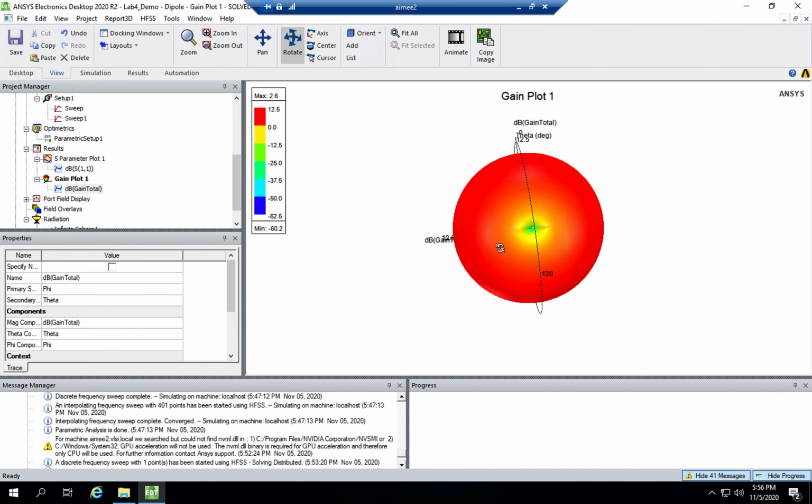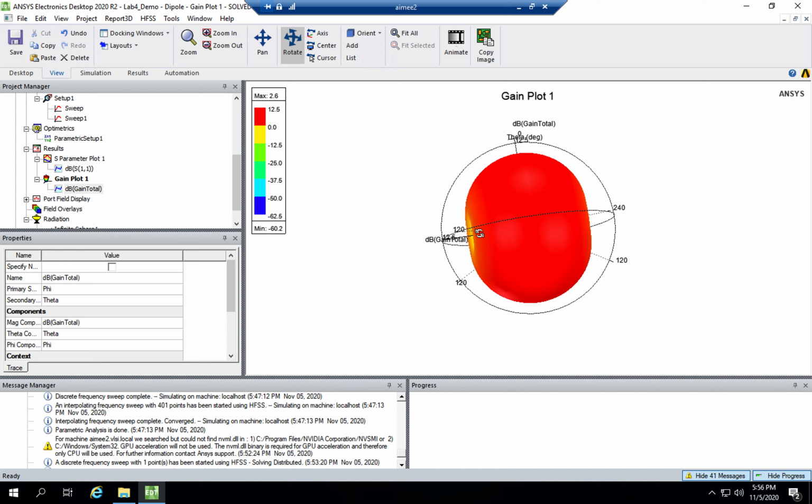So the first thing you would want to know is that there is a null along the dipole. So this null would be something that our principal cut should capture. And the cut that would capture this null is one that is along here. So if you cut, like a top view here, if you cut into the screen and take a certain cut here, you'll be able to see this null.